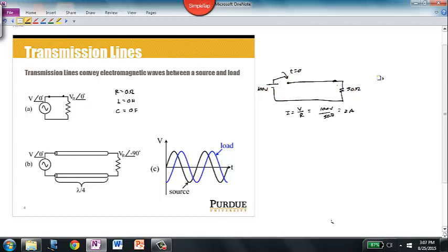However, this is not true. In reality, a voltage and current waveform is going to propagate along the transmission line from the source down to the load, and eventually the current value will reach 2 amps. Eventually. But this takes some finite period of time, and in the very, very short term, the current value anywhere in the wire can be less than 2 amps.